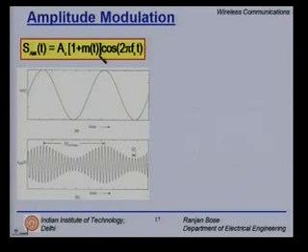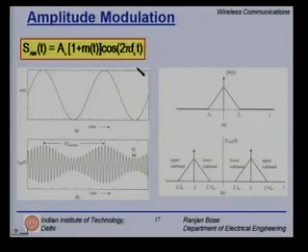In the frequency domain, you can have the message signal represented like this. So, clearly this is some arbitrary message signal, not a sinusoid. A sinusoid will put an impulse here. So, it is some message signal, and once you have an amplitude modulation, it is shifted to the location of the carrier. Okay. Hence, this gives you the need for twice the bandwidth required for your message.